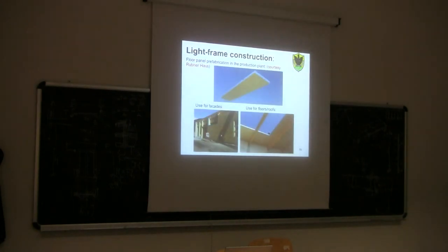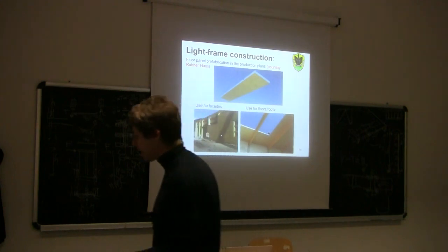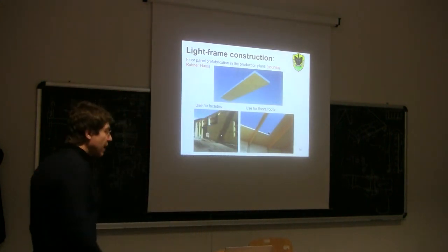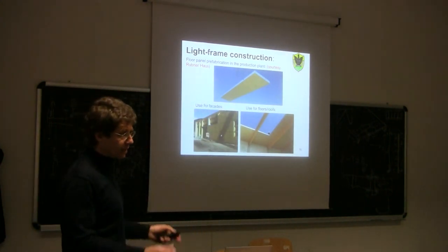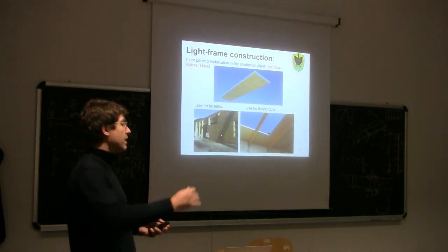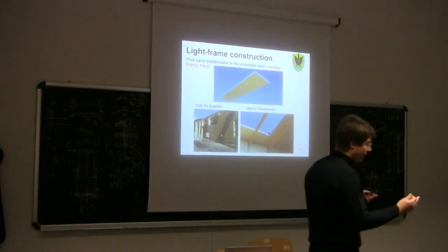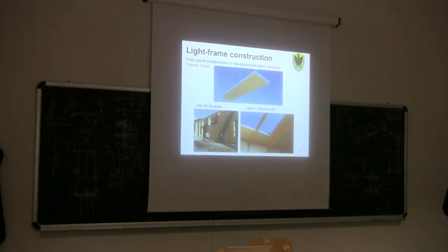Okay, so in Italy, I would say in Europe, you will always find, at this time, highly prefabricated light frame construction. Just a reminder that with this kind of structural type, as I said before, you cannot go as high as you want. The limit is 4 to 5 stories in a high seismic region, 7 maximum in a non-seismic region.